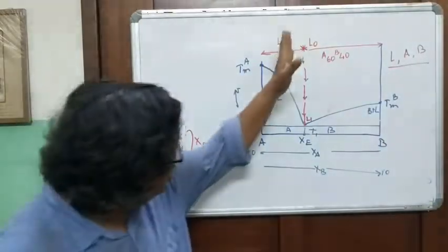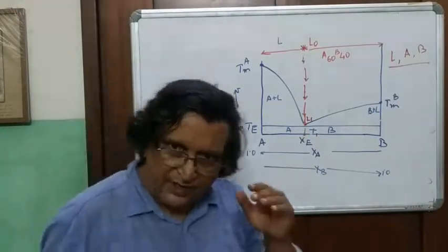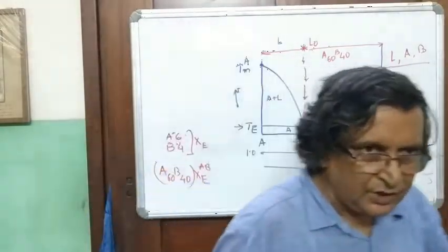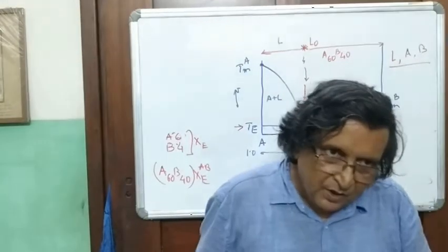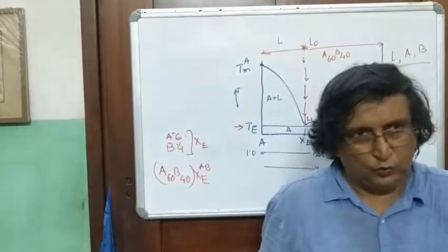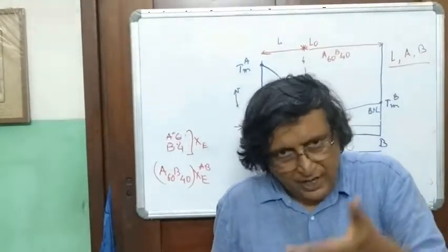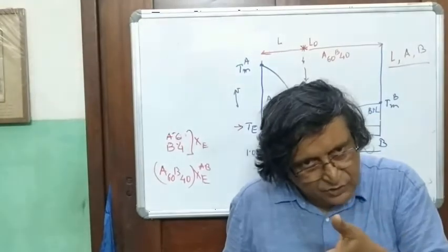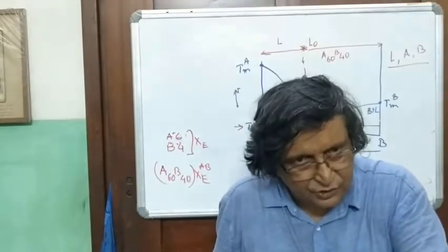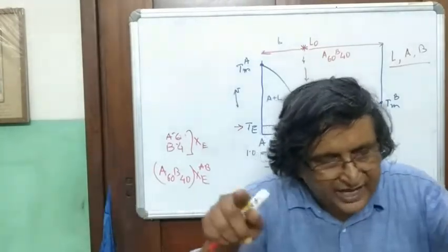But this is the only point in the diagram where the solid composition will have the same composition as the liquid all through its crystallization. The solid forming of A and B crystals will have the same composition as that of the liquid in terms of components A and B.